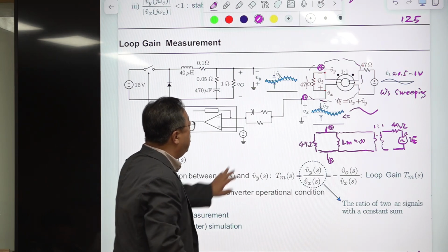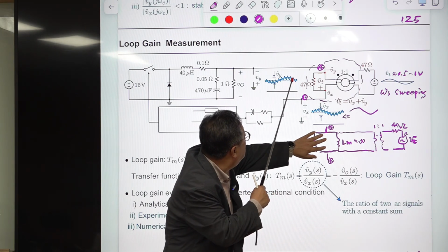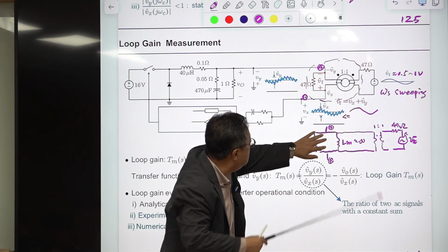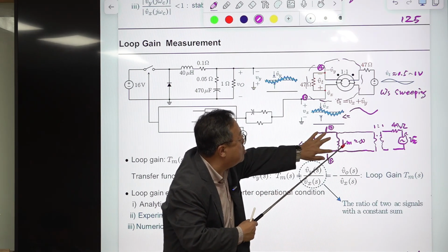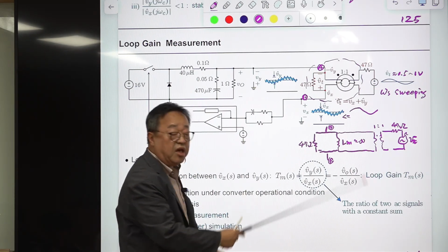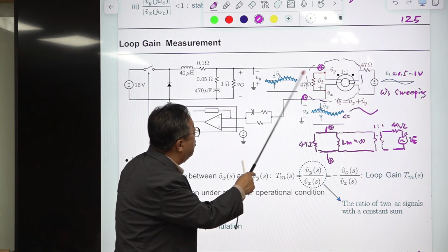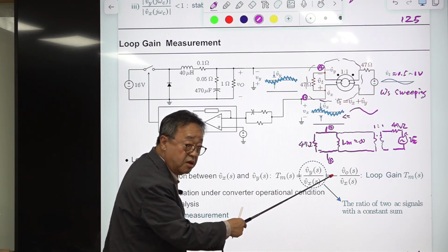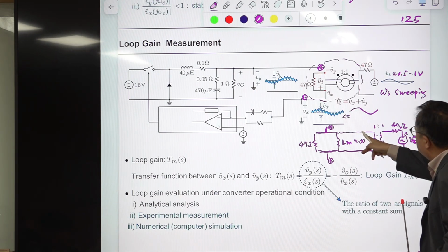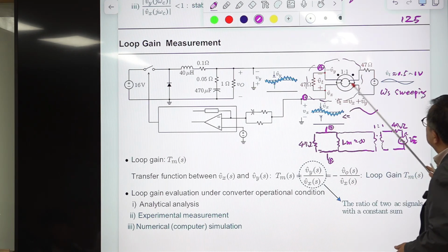All right, if there is no path here, then this will eventually be saturated, because there is some DC component in this current or voltage, and this DC voltage is applied across this. To avoid that, you need alternate paths for the DC or low frequency component of this current. So most of the current will be passed to this, right? And this voltage Vx will appear here because this is a 1-to-1 transformer. So this voltage is Vt. Okay, so define it this way.